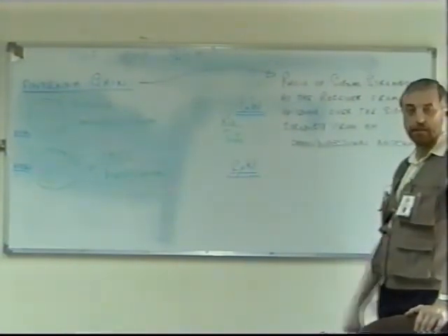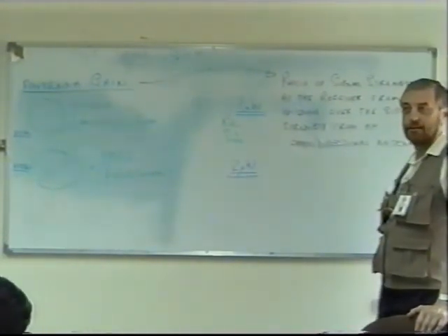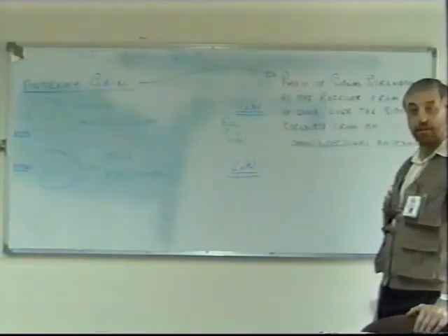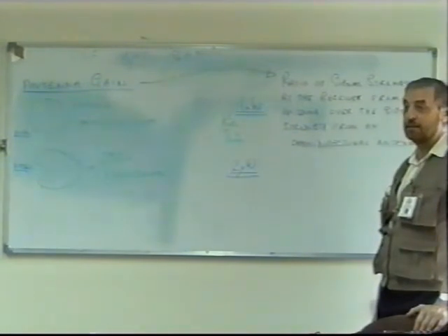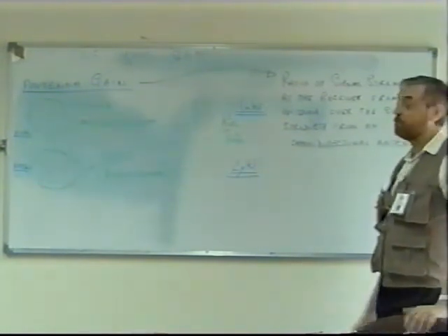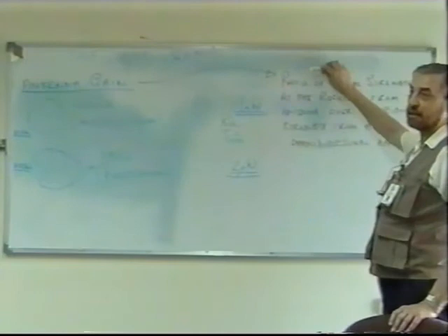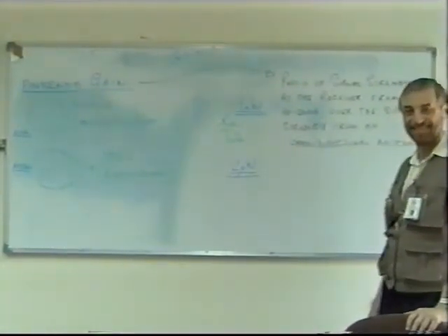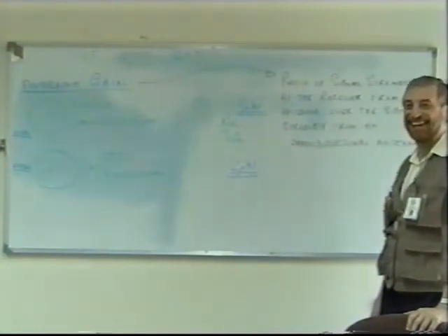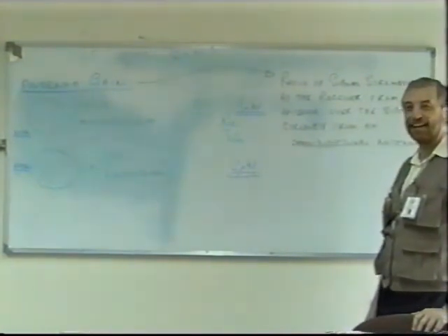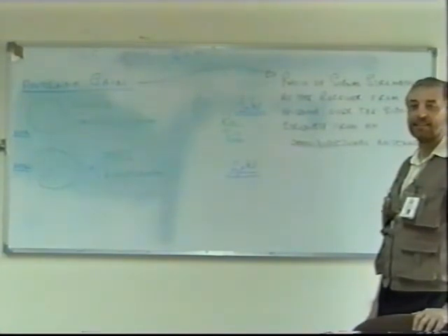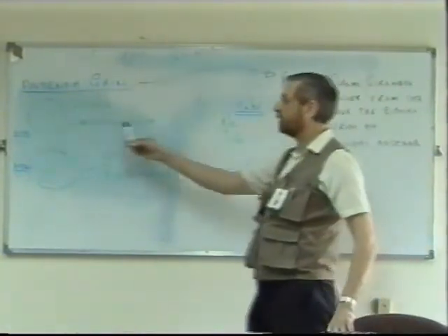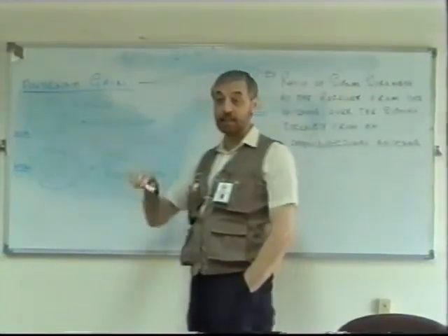Yeah, dipole, exactly. 0 dB? Normal dipole. A dipole has 0 dB gain because when we take the ratio of that power, it's 1 to 1. You're comparing it to a dipole. Well, if you're comparing a dipole to a dipole, it's 1 to 1. So it's 0 dB gain. All we're doing is comparing the signal strength from a dipole compared to that from a particular type of antenna.